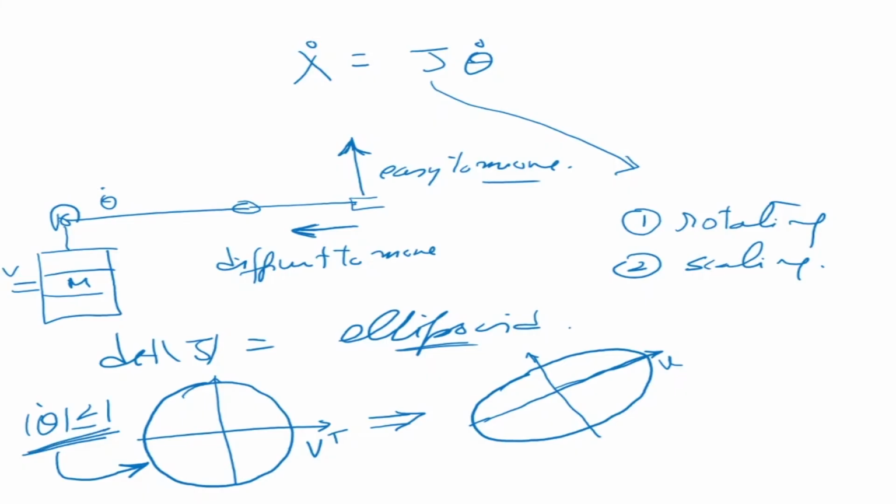This is the equation of a circle in 2D. In 3D it's a sphere. The axes are Vt in this direction, that is my velocities, the input. Now what is J doing? It is rotating this axis system. It was Vt, it has made it U like this.